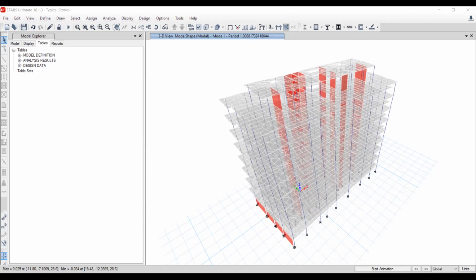which means we compare with 0.02, because it's mentioned that for a structure having a fundamental period of 0.7 seconds or greater, it should go to 0.02 for the drift. Okay, so this is the drift.